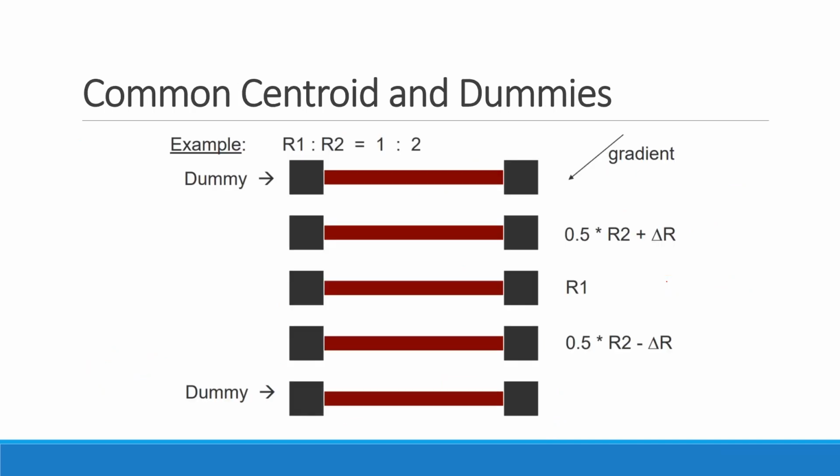Now, the other thing that I think Will or somebody had touched on was that there's another sort of error embedded there, which was, let's say there's just some gradient in the process. So let's say that on one corner of the chip, over here, I have a certain thickness of poly, and on another corner of the chip, I have a different thickness of poly. Okay? So if I'm going to be laying out resistors across that entire area of the chip, then I better be careful, because if I really want them to all match to each other, that's not going to happen simply because of that gradient in the process.